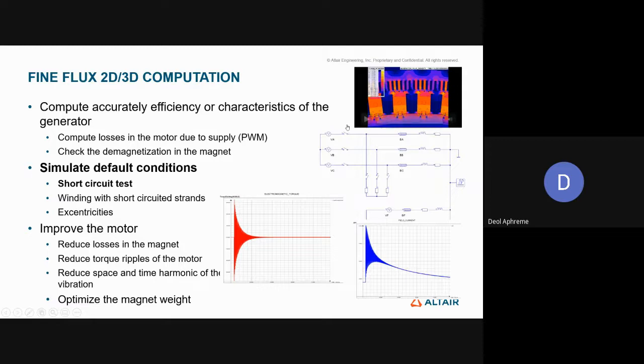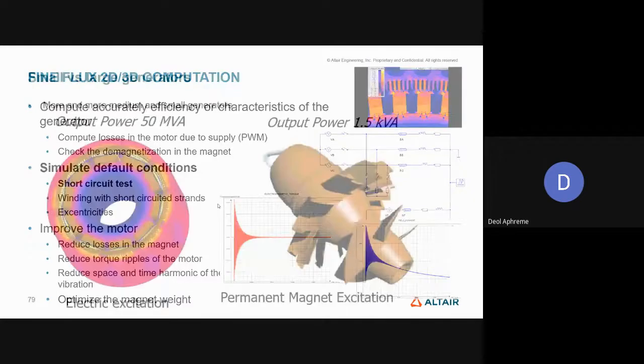And although I'm showcasing the motor characteristics, they also apply to generator characteristics, simply because demagnetization is a very real possibility that can occur. And if you have a field that is being inputted as a PWM field, that also can have a great impact on your generator. So there are different tests you would want to perform. If you are coupling your generator in series with some other generators, there will be a certain brief amount of time that it can go into motoring mode and all these things. So simulating all these things is very, very important and something that people usually consider most of the time.